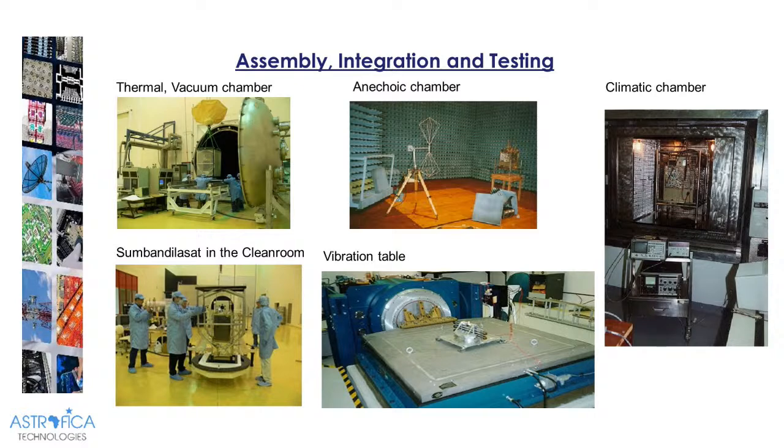So based on the information that you already have, that, okay, there's a CubeSat or a microsat of this size, and it's going to be parked at this orbital slot, and these are the temperatures that it will be experiencing, you then set those in your thermal vacuum chamber. The vacuum is mostly for outgassing, because we still use your harnessing as your normal harnessing.